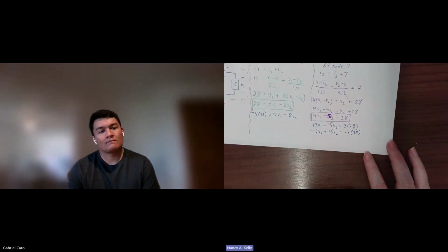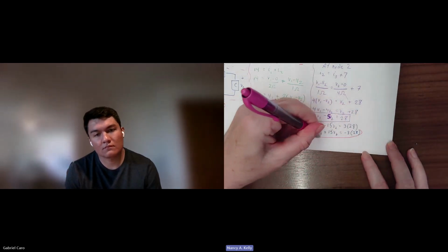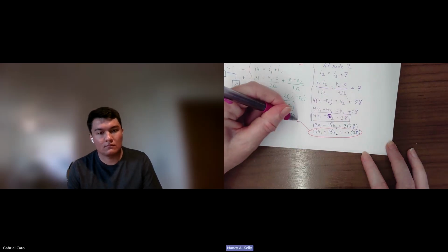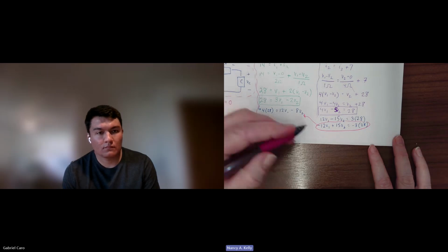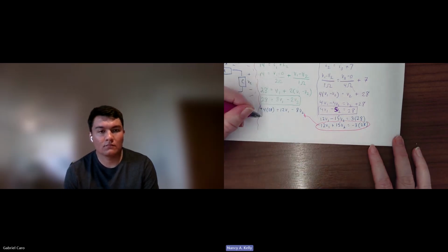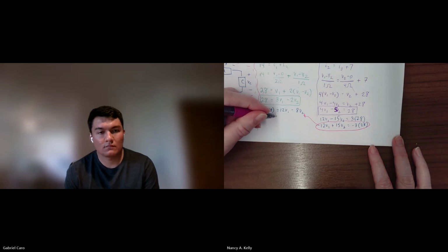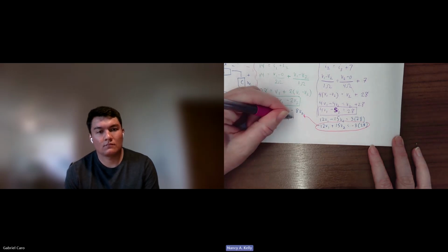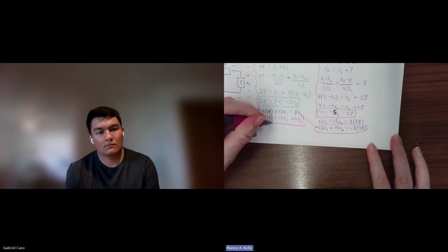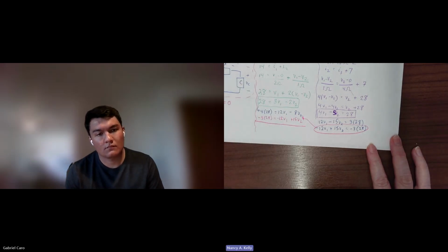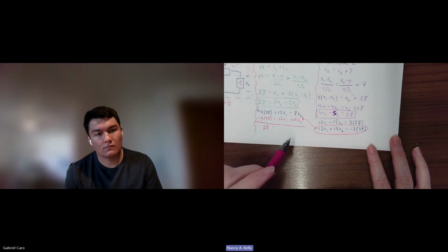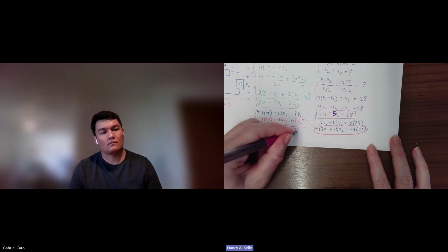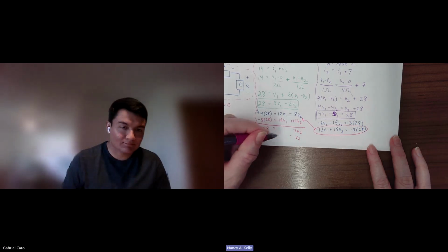Now, having done that, I'm going to take this equation here and add it to this one up here. When I do that, I'll put the minus 3 times 28 over here. Minus 3 times 28 equals minus 12 V1 plus 15 V2. And then I combine them like this. On the left-hand side, I'm going to get 28 equals, these 12 V1s go away because they add to be 0. And then I get 7 V2 here, right? I get that V2 is 4.